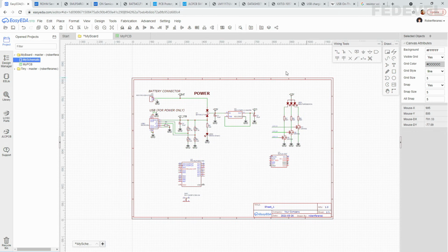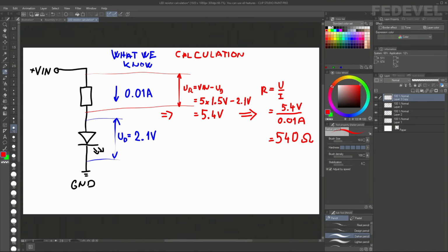In this real circuit, they may actually be a little bit lower, because the final voltage across the diode plus resistor may be a little bit lower than the 7.5 volt that we used for the calculation as the power input from these batteries. I just wanted to point out that even though we use a super simple calculation, it is still good enough to calculate the resistor value for this LED.